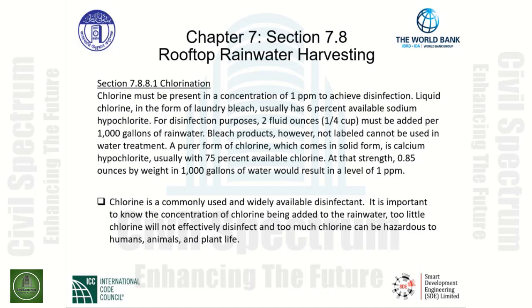We must be concerned with proper disinfection. Chlorination is indicated in section 7.8.8.1. Chlorine must be present in a concentration of 1 part per million to achieve disinfection.